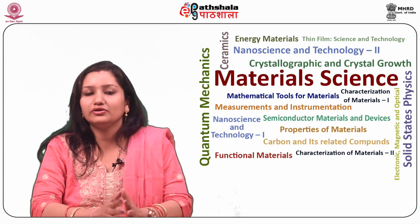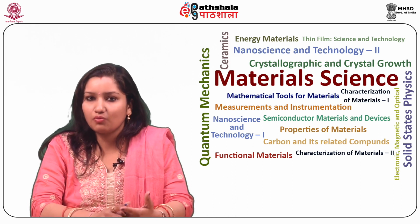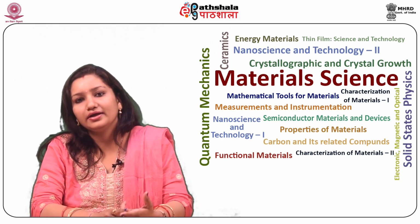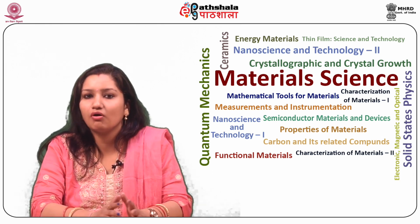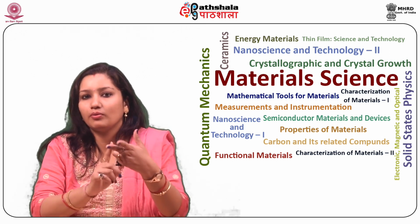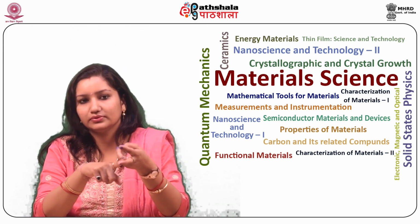Let us see why do we need thin film solar cells. Number 1, small thickness is required due to the high absorption, small diffusion length is required, and high recombination velocity is required for the high performance of a solar cell. And in thin film, we meet all these criteria. Secondly, materials economy, very low weight per unit power is required, which is again fulfilled by the thin film solar cell.